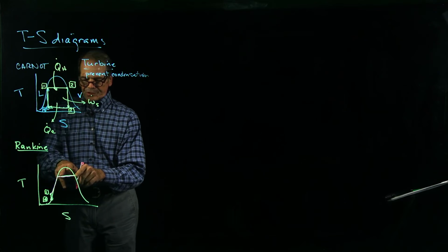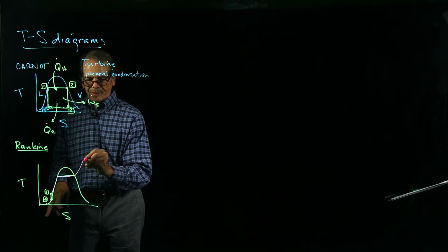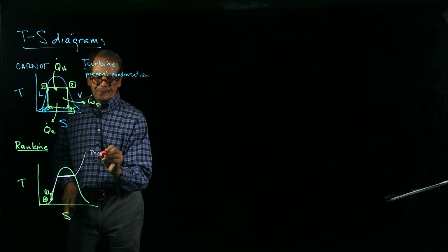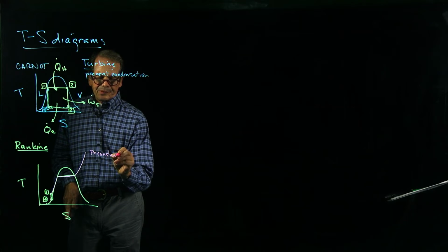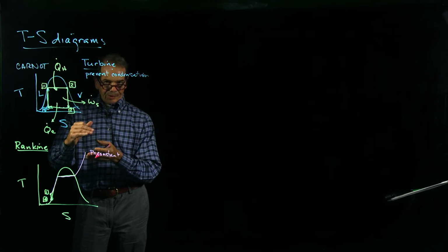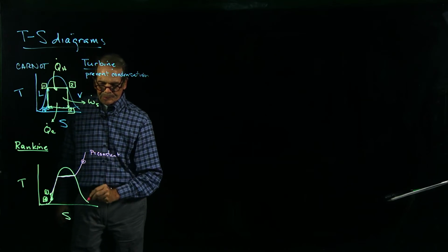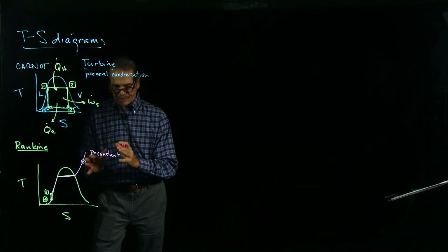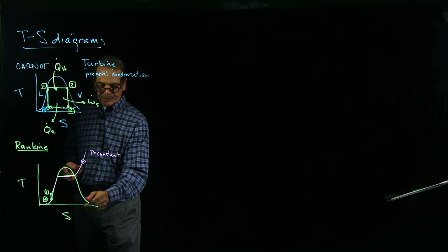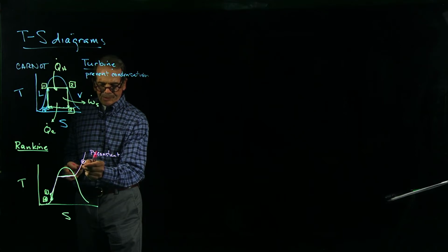And then, this is at a higher pressure, so I'm going to heat it along an isobar to a higher temperature. And I'm going to heat it up, as we said, so it's supercritical. No question. It's going to be up here, because when I condense it, I need to condense it down to a lower temperature. This is going to be an isentropic condensation.